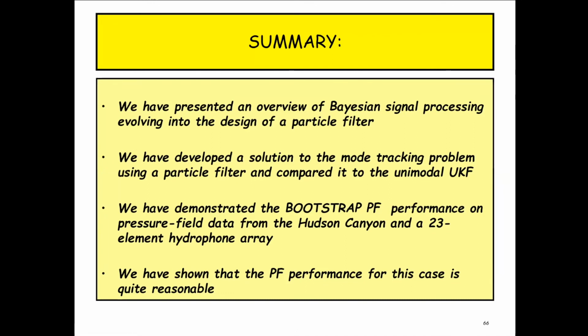So we presented an overview of Bayesian signal processing evolving into the design of a particle filter, which is a sequential Monte Carlo technique. We developed a solution to the mode tracking problem and compared it to the unscented Kalman filter. We demonstrated the bootstrap particle filter on a pressure field from Hudson Canyon, and we've shown that the particle filter performance for this case is quite reasonable. So that's it. Thank you for your attention.